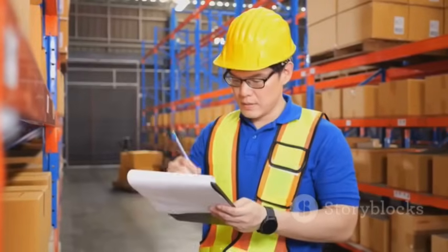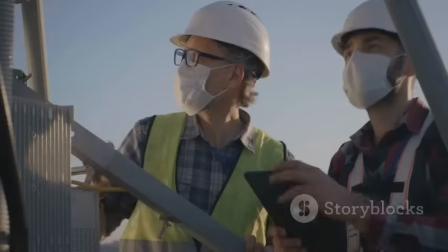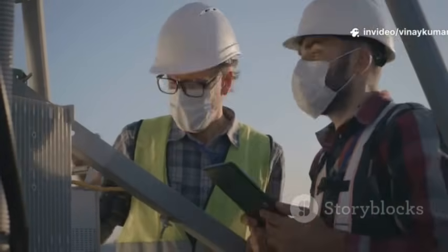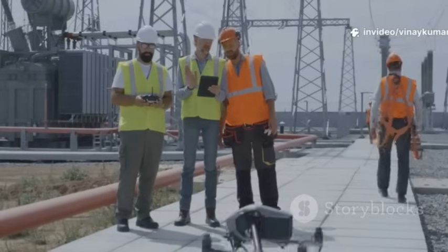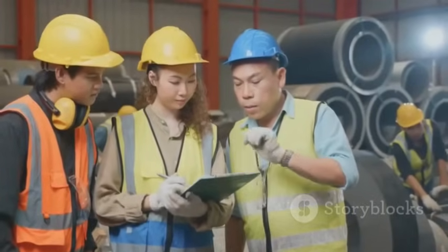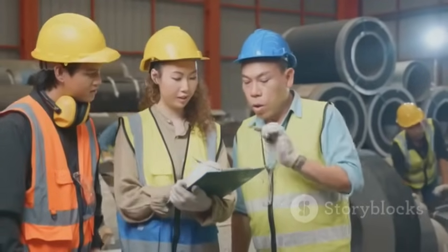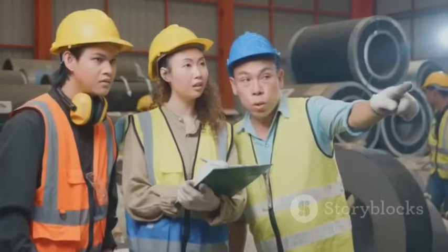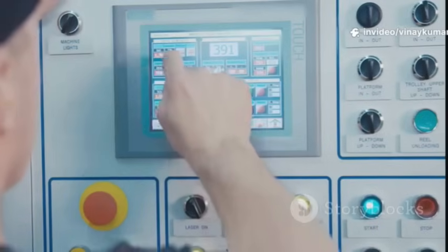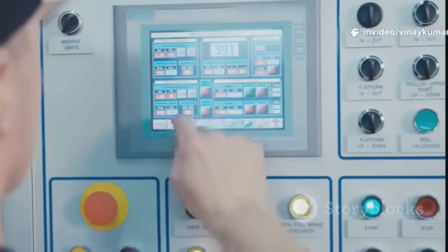The review must confirm several key things. First, that construction and equipment are in accordance with the design specifications. This is often done through a physical walk-down of the system. Second, it confirms that all the necessary safety, operating, maintenance, and emergency procedures are in place and are adequate. You can't start up if you don't have the instruction manual ready.